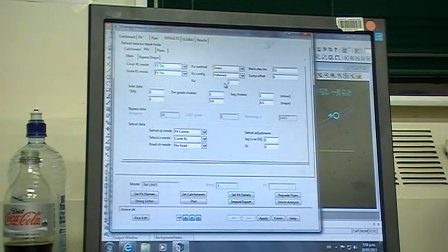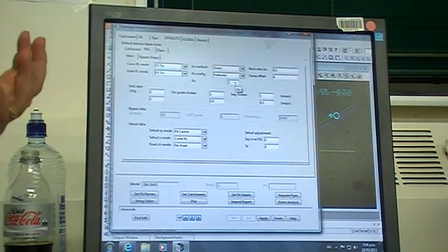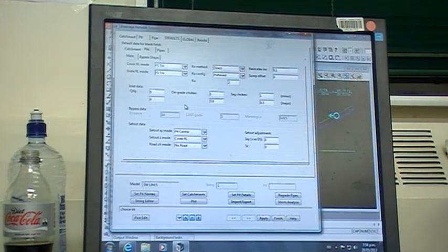KU method is the loss through the manhole. You can either go through and, under the council standards, work out for each pit what it is, or I find if you just stick to the default there of 2, it's conservative, but it gives you a design. Then if things are a bit pushed, you can always go back to the individual manhole, work out what it is, and pull it back if you've got the flexibility. I like to go for a factor of safety in these things. It means you're slightly over design, but there's nothing worse than the first time it rains having manhole lids pop off your drains. You look like a bit of a knob.